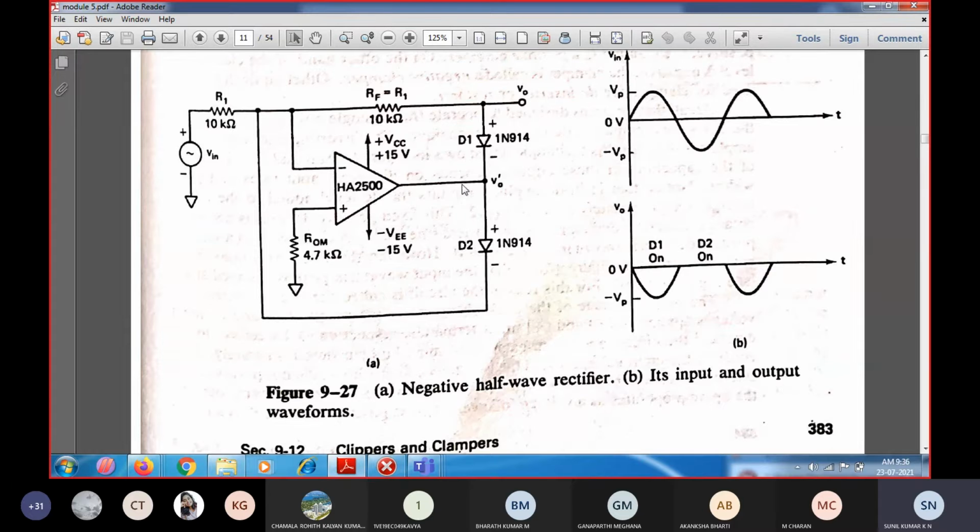So you can see this is the negative half cycle of the input, so the op amp output is going to be positive going, here it will be positive going and here it will be negative going, so both will get settled at virtual ground. The output from the op amp as well as the input signal will get settled at the zero level, and hence both get cancelled, and since we are going to take the output from this point, the op amp will not get saturated in any direction.